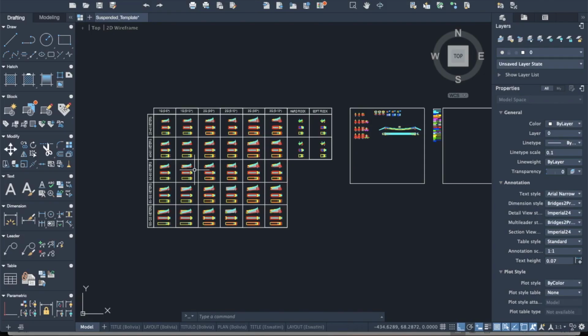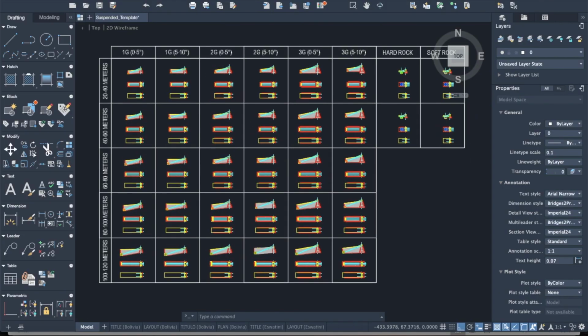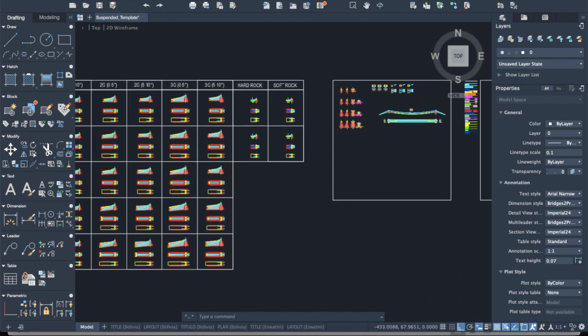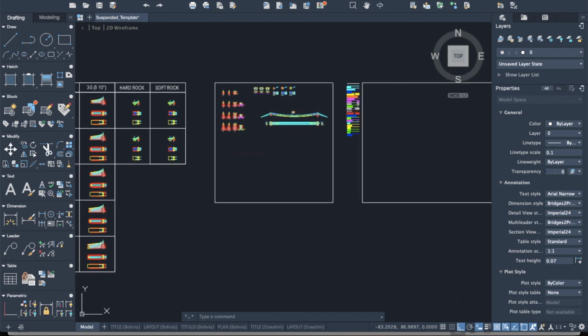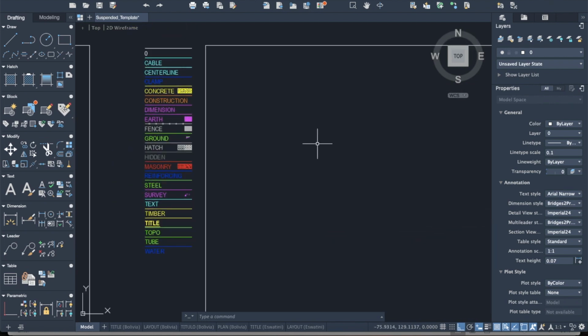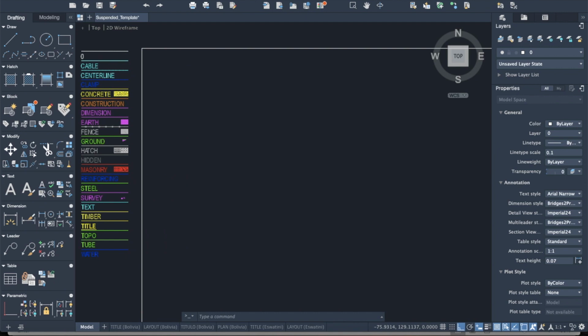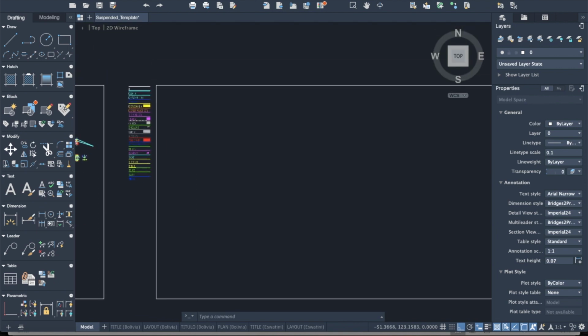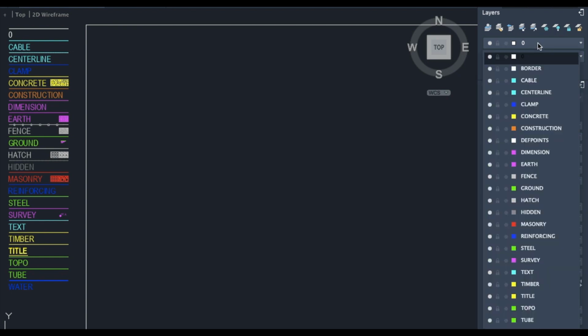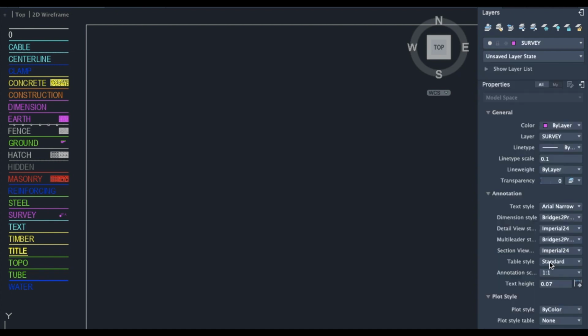This is EIA's suspended bridge template. It includes the generic abutments used for suspended bridges, as well as other guides and templates which help students design their bridge on AutoCAD. EIA requires all students designing a bridge to use this template. While the abutments are not applicable to West Virginia bridges, many of the other features in this template will be used. Here are EIA's preset layers. You should change your layer depending on what you are drawing. In this case, we will be drawing survey data, so you should select the survey layer.